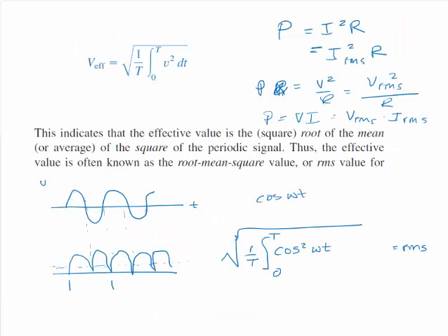People sometimes forget in the lab that your voltmeter is measuring RMS, that the formula VRMS equals 0.707 times V peak only applies if you have a sinusoidal function. So the RMS value that you'll get is different if you have a triangle wave or different if you have a square wave that you're trying to measure.